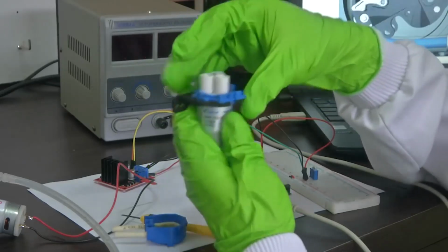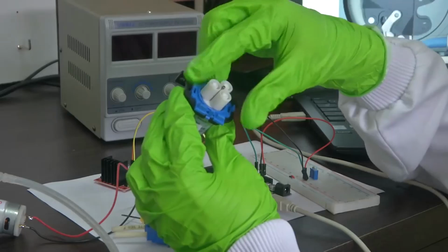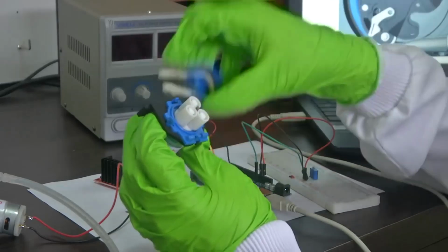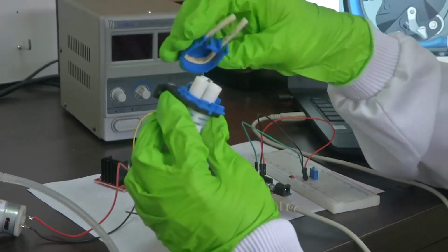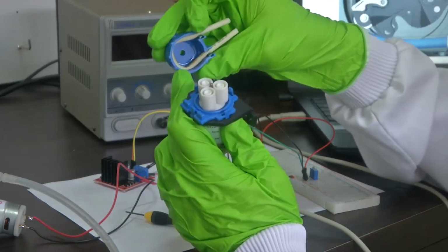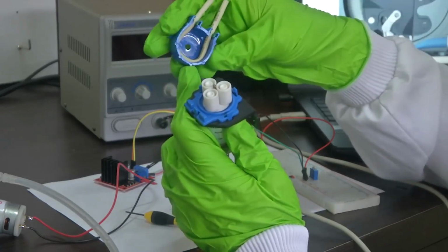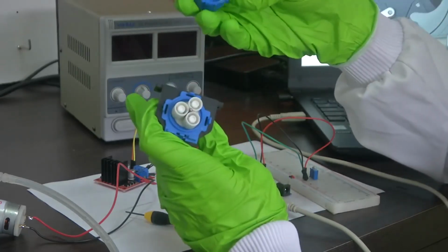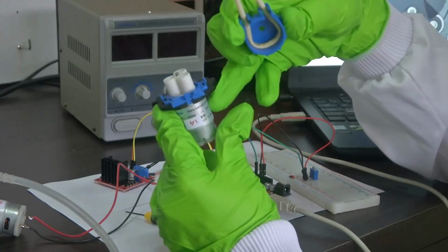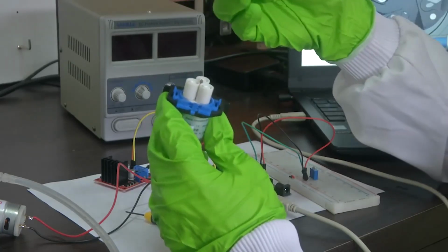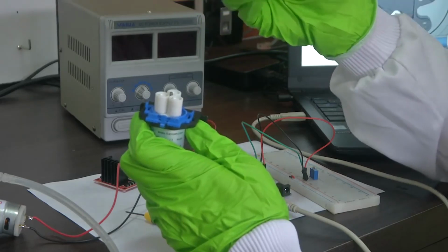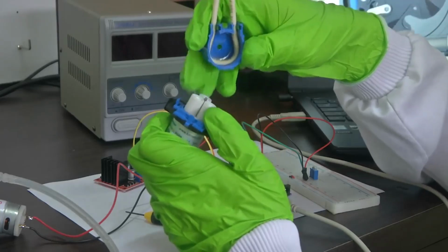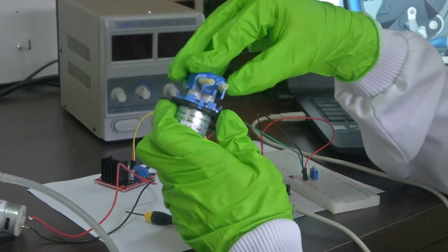Now if we give power supply to the motor, this roller unit entirely will start to rotate. The tube that is going to come over here will be compressed. You can see the tube is being pressed against and it has deformed, but it will still work. So this is the internal construction of a peristaltic pump. It's nothing but a DC motor, but with a different construction: a flexible tube, an outer casing to hold the flexible tube, and the rollers attached to the DC motor. So I'm just putting it back.